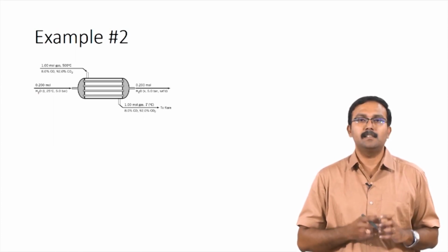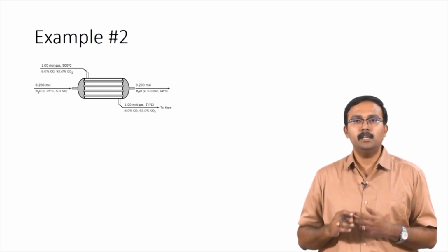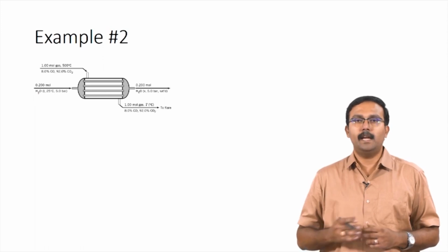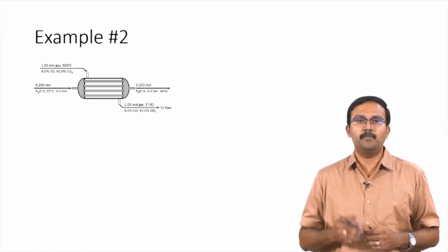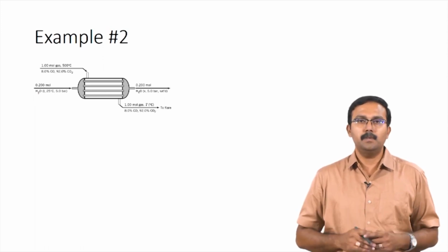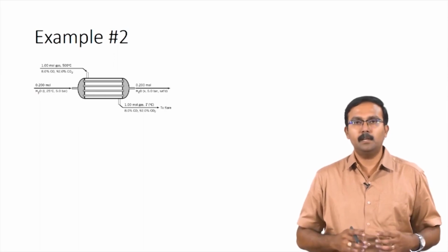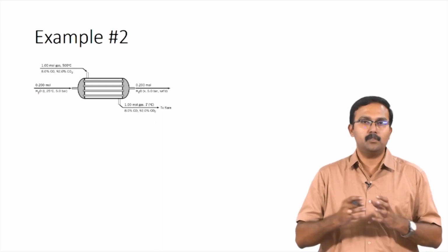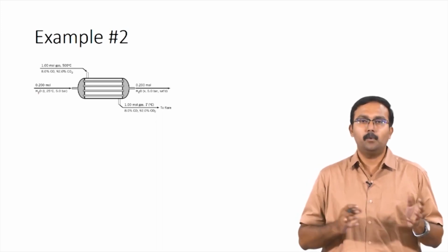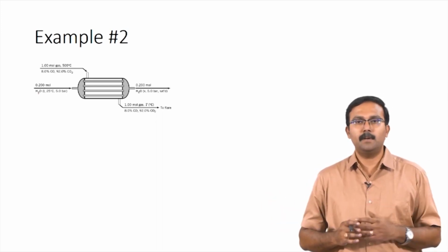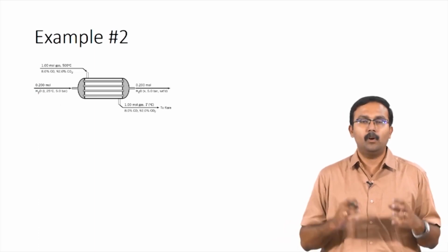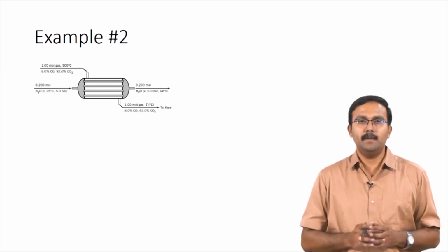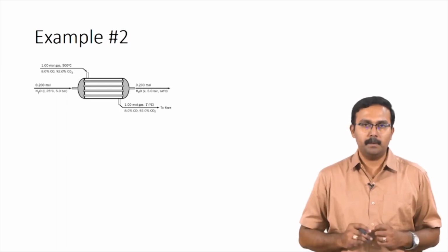So, the phase change is negated because we are using steam tables. As always, the first step for any energy balance problem is to perform material balances. However, here there are no material balances required because the carbon dioxide carbon monoxide mixture which is coming in does not come in contact with water, and water leaves separately, carbon monoxide carbon dioxide mixture leaves separately, and all the information about the compositions are also known. So, we can ignore any material balance calculations that might have to be performed.